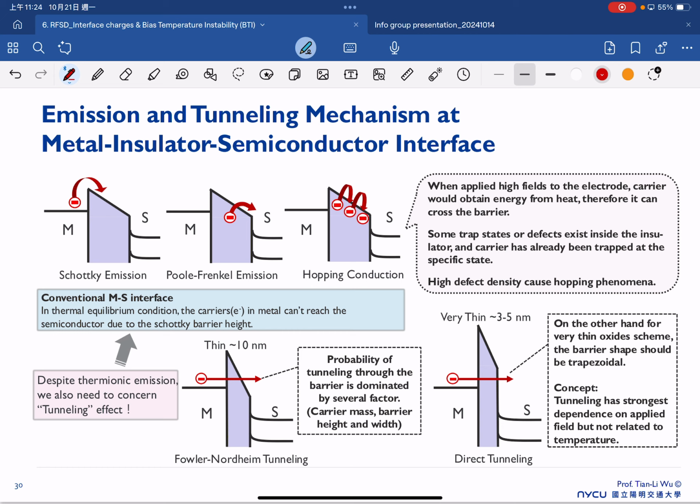I admit the lecture slide I proved it there because there are so many old literatures. Sometimes the figure quality is not that good, but the point is that it can give you good motivation to improve them and make them your own thing. So that is one example. In this slide, it's very clear, and the conclusion is the same. So if you have a thick dielectric, roughly 10 nanometers, you have FN tunneling, but if it comes to very thin, you have the direct tunneling.